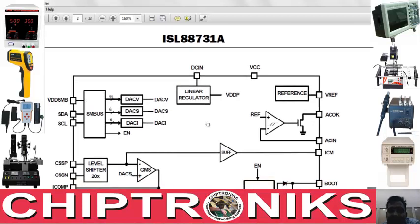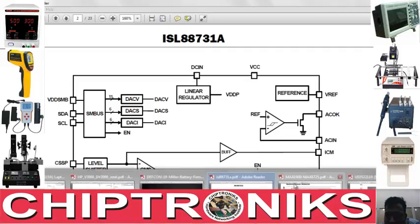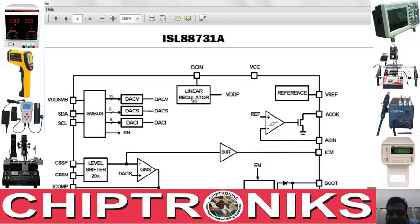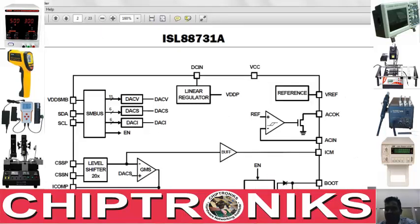Similar to the Maxim 8725, the important pins are DC in, AC in. Like we see over here, DC in, and after DC in, it's an input to an internal linear regulator which generates a voltage VDDP. Similarly, over here it generates LDO. So both of them are quite similar.